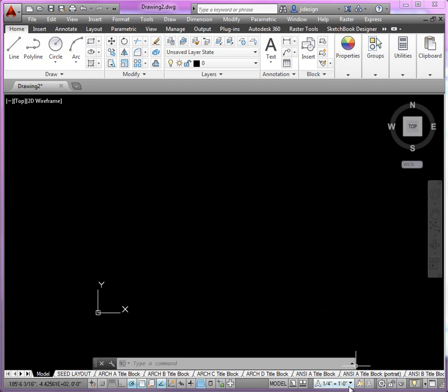So if you look down here in the status bar, we can see that right now 1/4 of an inch is equal to 1 foot. And we want to make sure we turn this to blue, this button here, which is our annotation visibility control, and we want to filter out everything else. So we just want to focus on the annotations created for 1/4 inch scale.